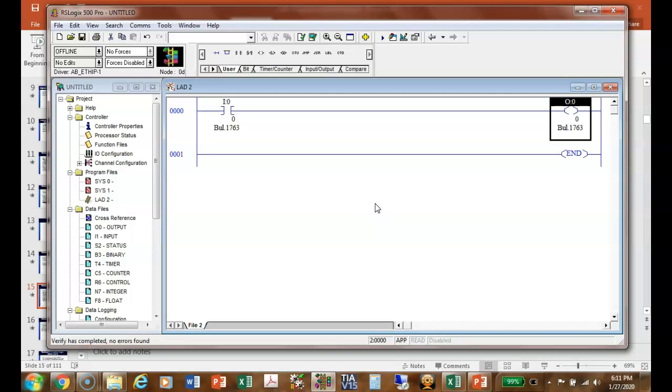So every rung has to have an output. Outputs are required. We do have things we call unconditional. They have to happen every time. So anytime I put an input over there, it's going to be conditional, which means certain conditions have to be met before the output is true. There are some situations where, if I wanted to turn on a light anytime power came on to those 2 rails, then I wouldn't put an input, I would just put it between L1 and L2, right? Every rung has to have an output. Inputs are usually going to be there, but they don't have to be.